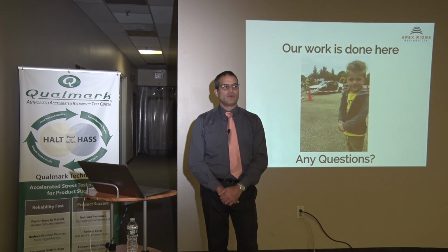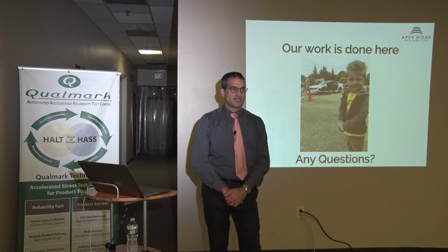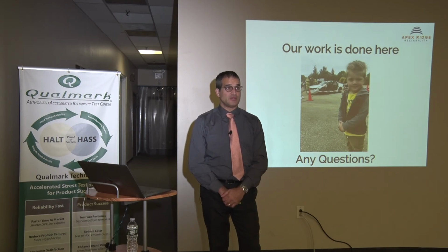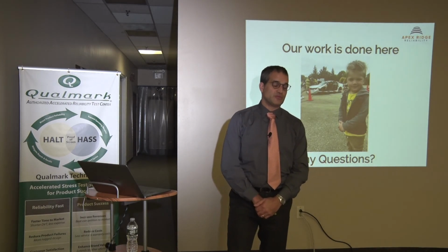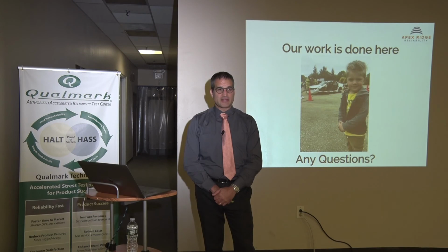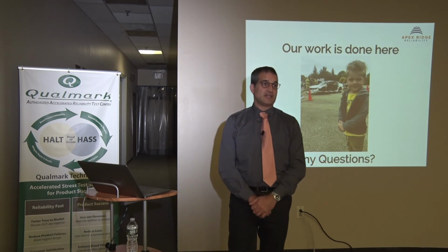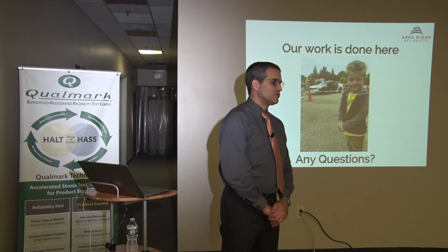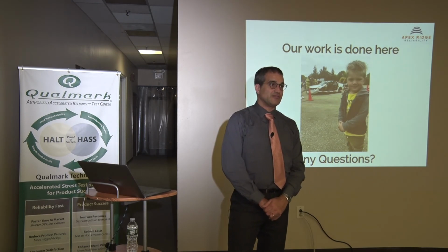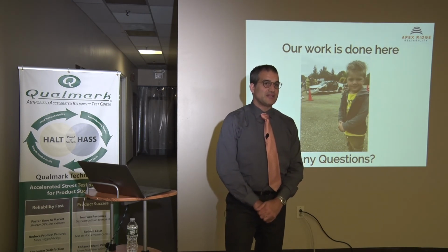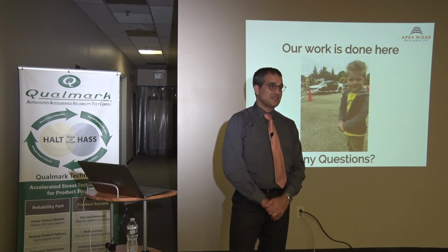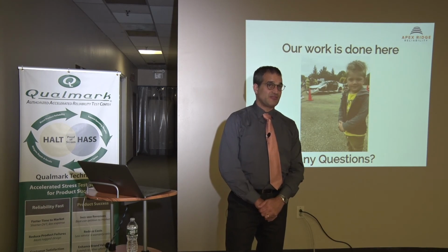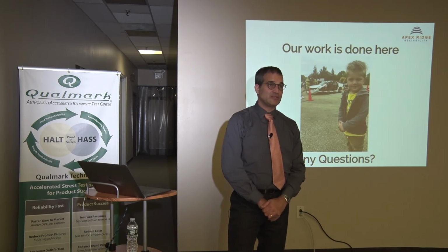So the question was, how does sample size come into play with HALT testing with regard to getting the variability and statistical confidence, and then with regard to that, using it as input for Weibull testing? Well, this is another thing that differentiates HALT from a lot of other testing, the reduced criticality of sample size. And this goes with that principle, again, of we want failures. We're not looking to draw statistics on percentage of pass and fail. We're hoping to fail every single unit.